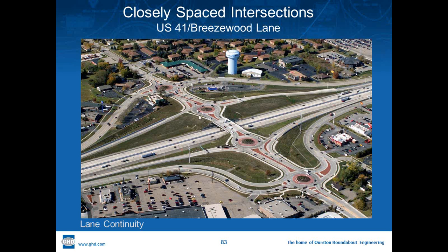And if you want to keep these compact, you can look at the valving and effectively impeding some of the approach flow, not excessively, but impeding it such that you don't require 3-lane entries downstream, as the combination of the ramp traffic and the frontage road traffic could contribute to a different lane configuration at the ramp terminals. And we want to keep ramps free and clear for the mainline system. So there's different ways to approach it, but it should be evaluated as a system.